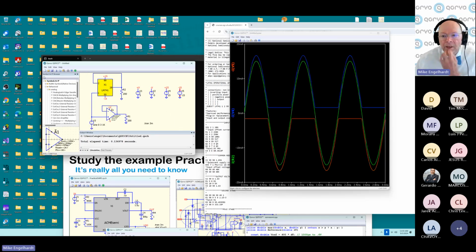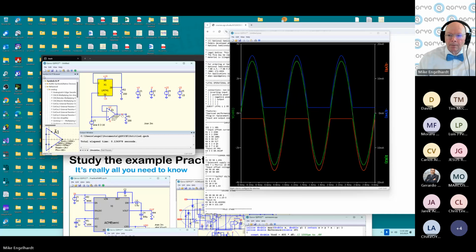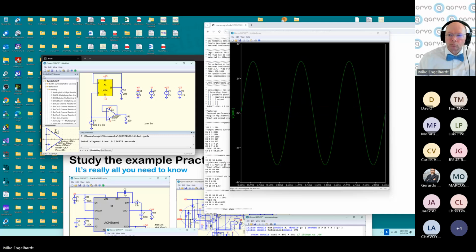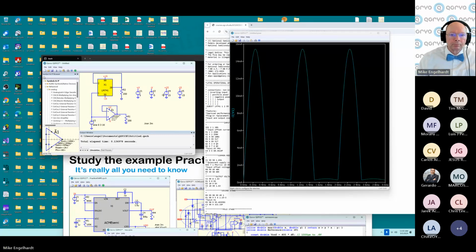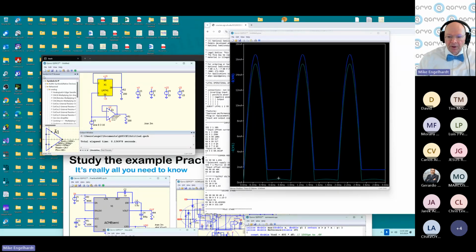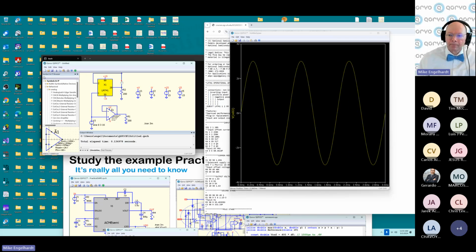And this one is doing not too bad on steering the current about the rail. So this is a little bit above average op-amp model, but that's how you'd use the 741. The 741 has more quiescent current. The default device is a fairly low quiescent current here, but that is including a third-party model.